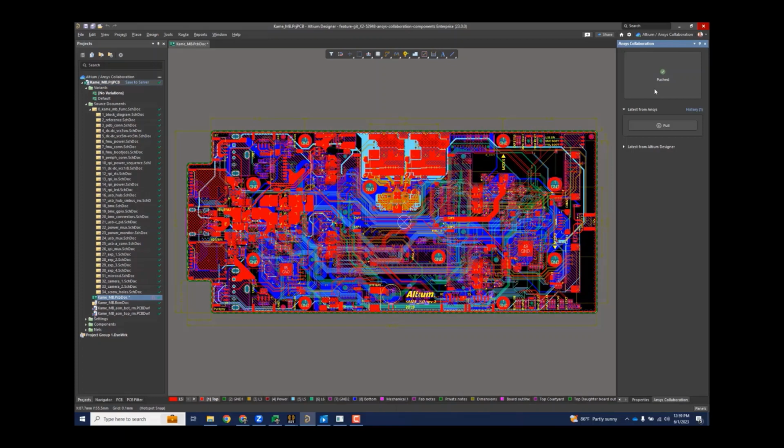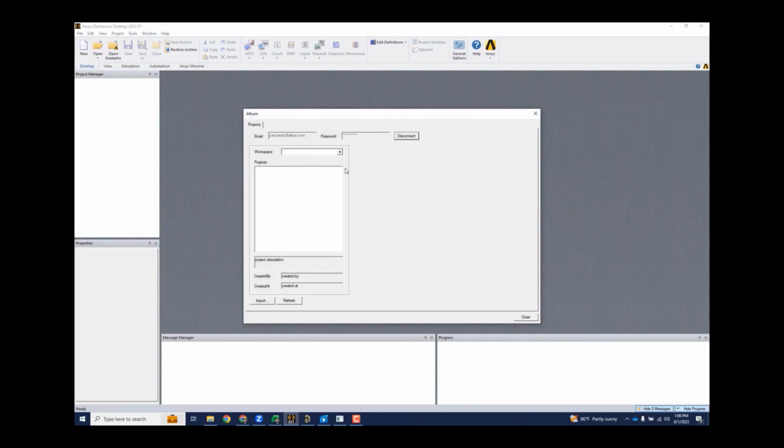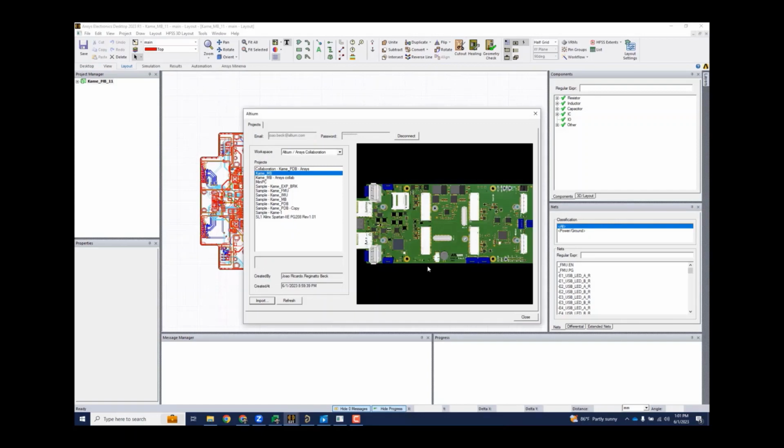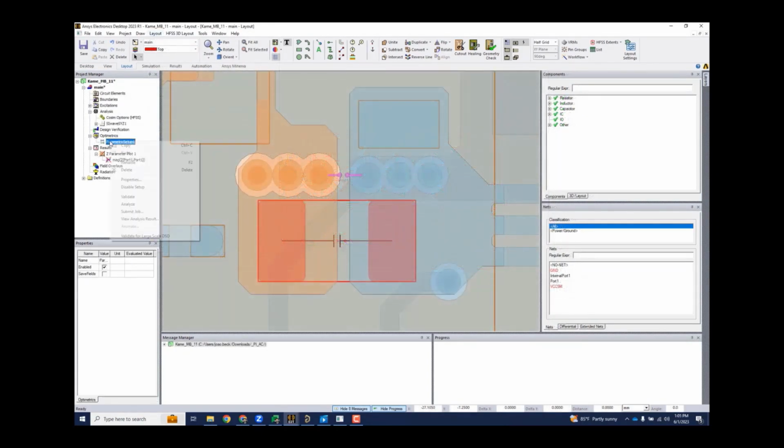Now this workflow begins in Altium and it uses the standard push-pull workflow that we all enjoy from MCAD. And once you're in Ansys, you can then pull the exported project into Ansys. So all of this works without file sharing. You can then create a local project and then proceed to go into your analysis. Here we're just showing a simple power integrity application.